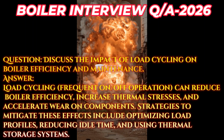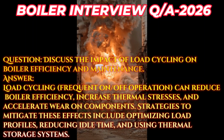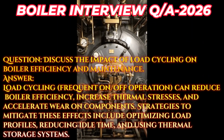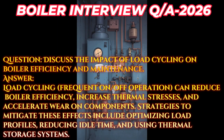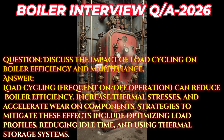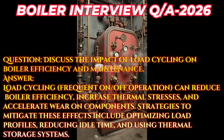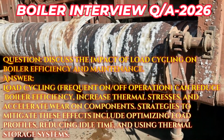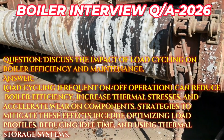Question. Discuss the impact of load cycling on boiler efficiency and maintenance. Answer. Load cycling, frequent on-off operation, can reduce boiler efficiency, increase thermal stresses, and accelerate wear on components. Strategies to mitigate these effects include optimizing load profiles, reducing idle time, and using thermal storage systems.